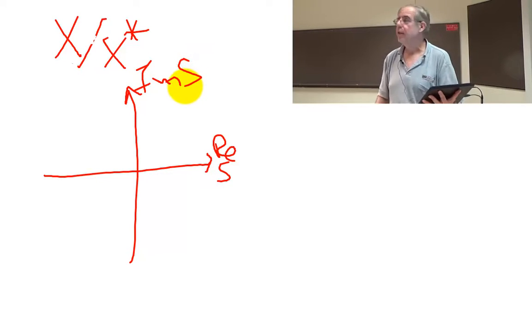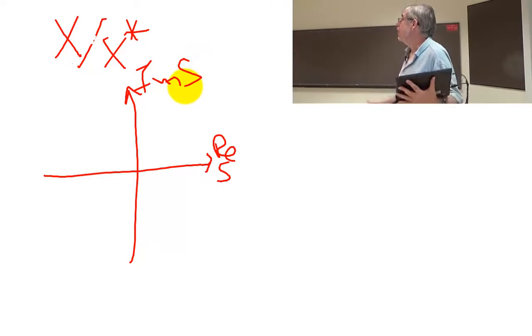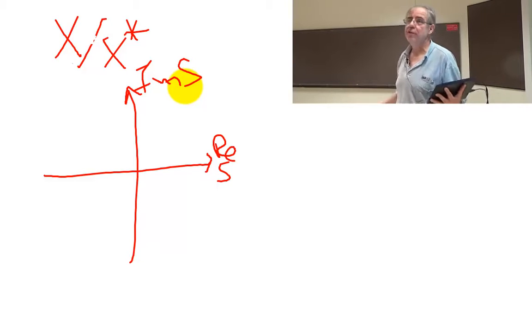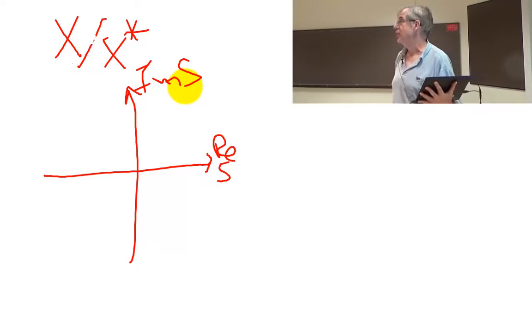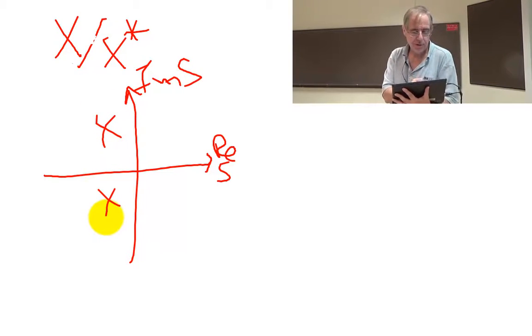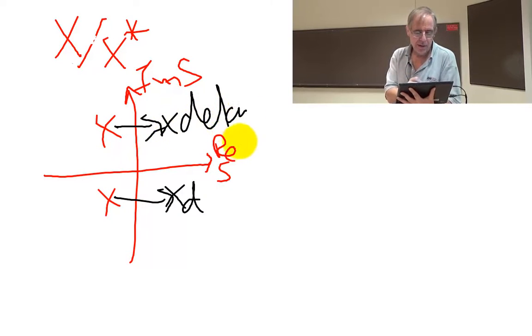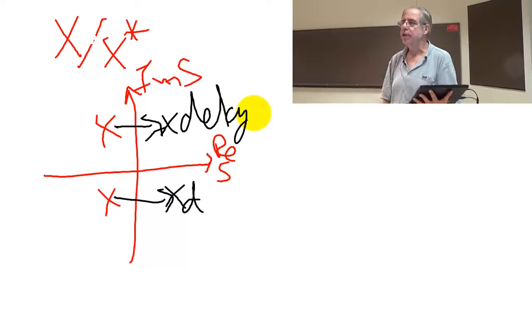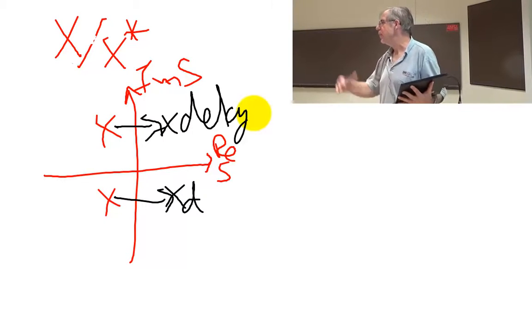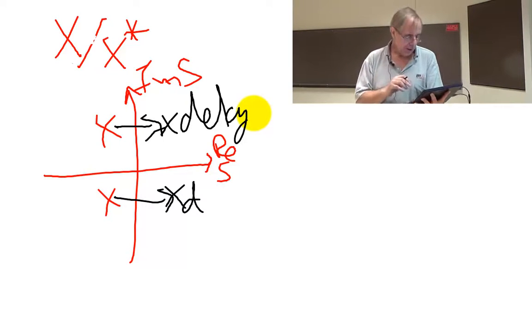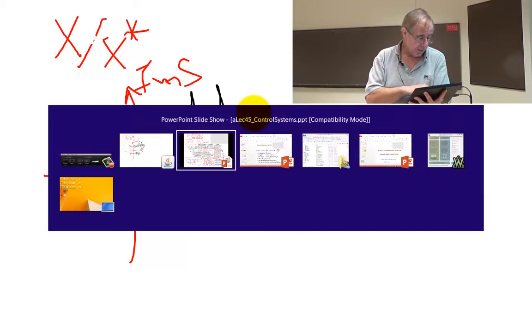And what do you want to see? What are some good things? Poles and zeros, right? Where shall I put the poles? Left. Yeah, you want to put the poles over here. And you know what that delay does? Moves the poles over here. If the delay causes the poles to shift over into the wrong half, it becomes unstable. Right? So the delays are bad.